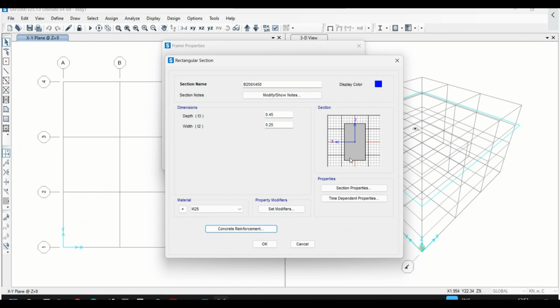For columns, there will be rebar layout. Next, we will design that after this. But importantly, look at the local axis shown here, 2 and 3. This is important. You need to know the local axis of each element type. Work with the SAP because you need to rotate or orient in certain angle as per your model needs.